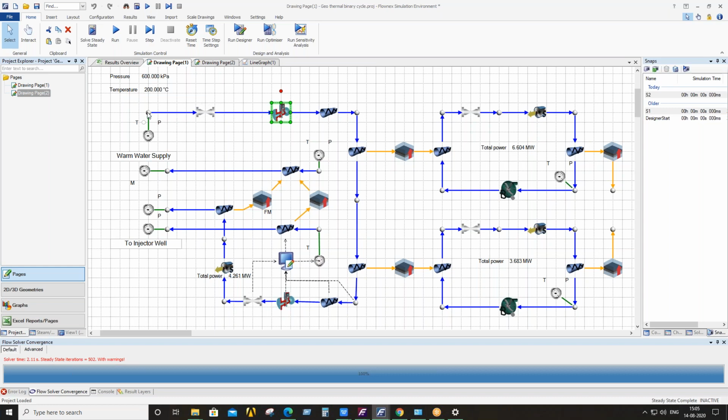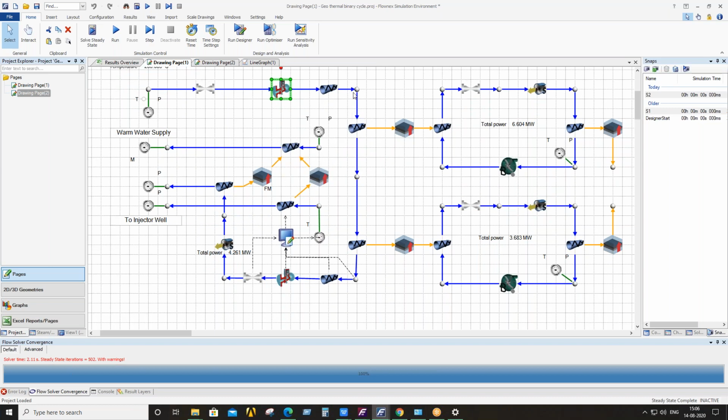since it is already in the superheat region, there is no need to separate the steam, and it continues in this line. Here you can see there are two small cycles. Actually it is the Hexane cycle, which means another liquid is utilized. It is also a Rankine cycle, but instead of getting heat from coal or gas, it exchanges heat with this